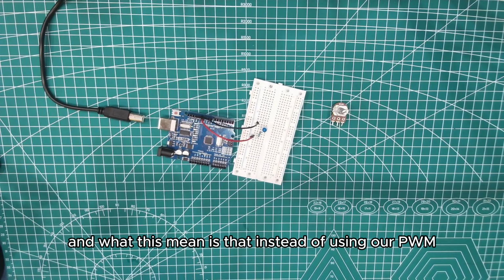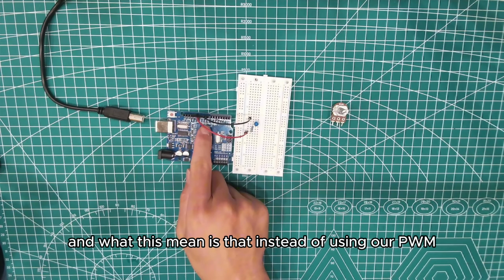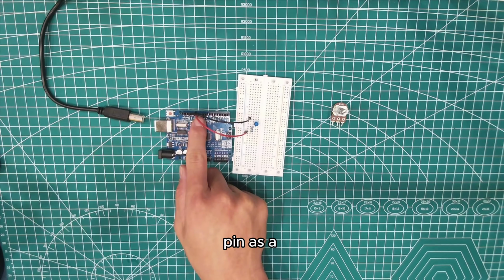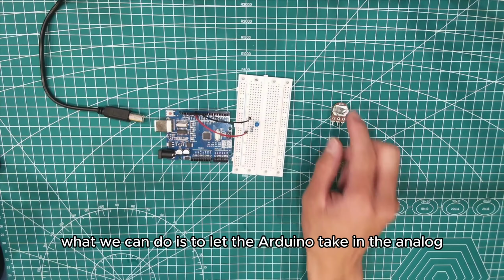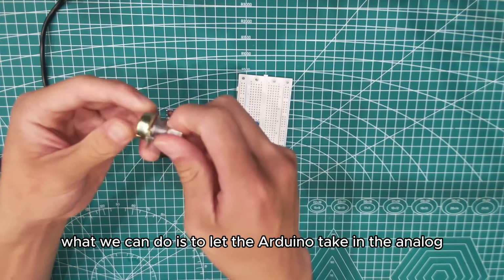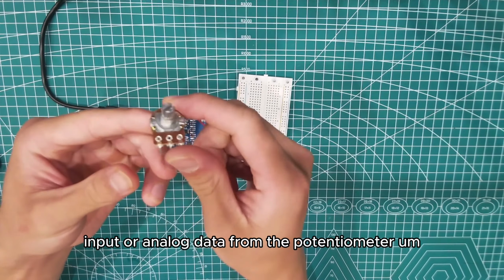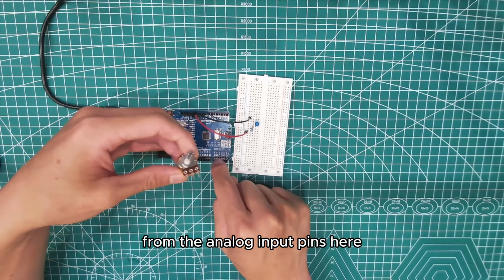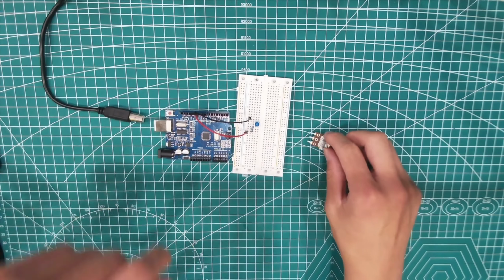And what this means is that instead of using our PWM pin as an output pin to control the brightness of our LED, what we can do is let the Arduino take in the analog input, or analog data, from the potentiometer from the analog input pins here and control the LED in that way.